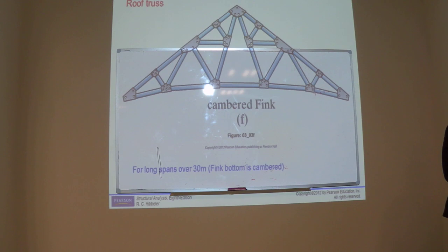For bending moment. For long distance. But what is the benefit of cambering? Less bending moment. To concentrate the loads on the joints, two joints. Resisting moment. It has two benefits. It increases the bending capacity, and it decreases the deflection.